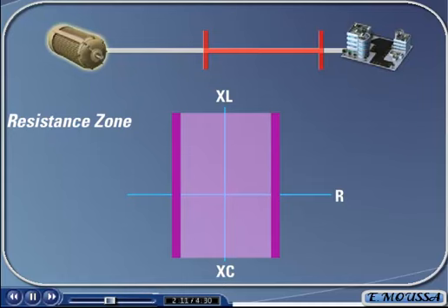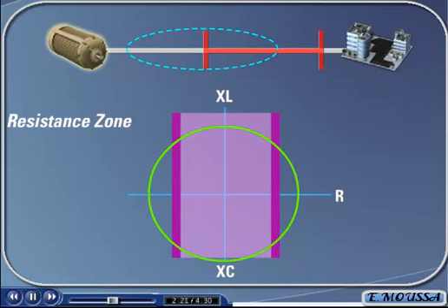transmission line. This type of zone is usually never used to trip a transmission line on its own, but is normally used to supervise another distance zone of protection. For example, if an impedance zone detected the impedance of the line just slightly enter its zone of protection due to a fault occurring towards the end of its zone of protection, the resistive zone can be used to verify that the fault is actually on the transmission line, because the impedance of the fault is mostly inductive. In this configuration, the resistance zone would be giving the impedance zone permission to trip.